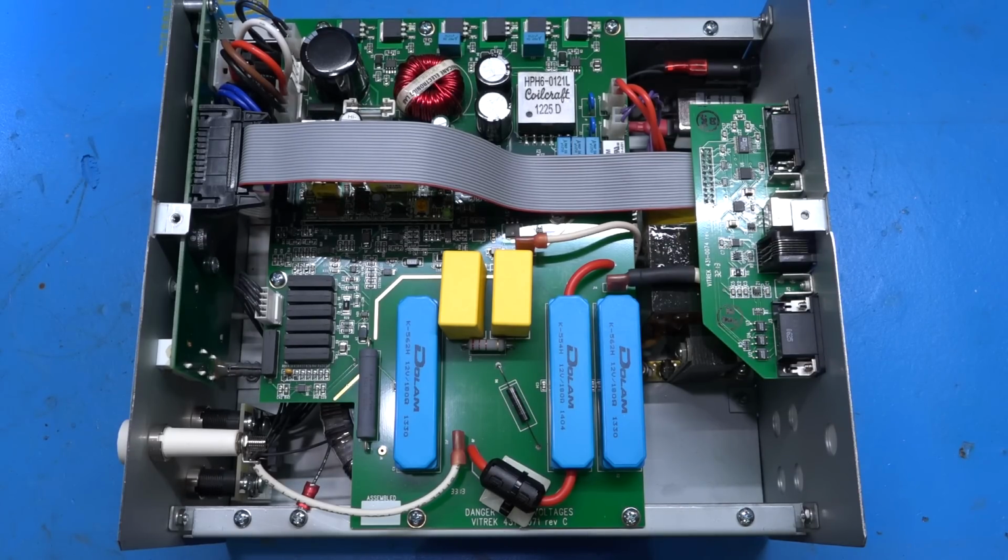And here is what's inside of this HiPot safety tester. Now, as you saw, this instrument can either give you AC or DC, never at the same time in any combination. As a result, the output is essentially a reconfigurable high voltage selector. You either send the AC signal through or you pass it through a very simple rectifier to give you the DC voltage. So as a result, this is still significantly simpler than the amplifier we're working our way towards.